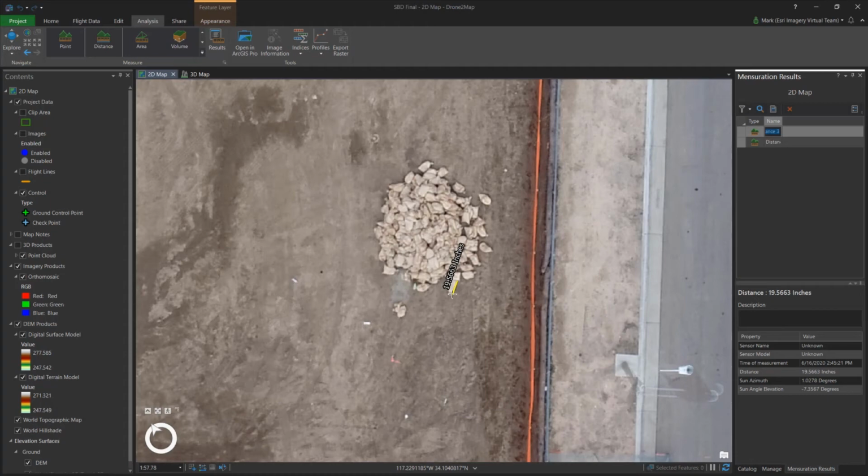Next, I'll use the cut and fill volume tool to calculate the total volume of the pile of sandbags. The cut and fill volume tool is calculated from the difference between the digitized feature and a base surface. This base surface is interpolated from the elevations at each vertex in my sketch. So I'll create several vertices around my pile of sandbags to make sure I have a good sampling density. Now that I have the total volume of sandbags, I can multiply 70 by the total cubic yards to estimate my sandbag count at approximately 385.